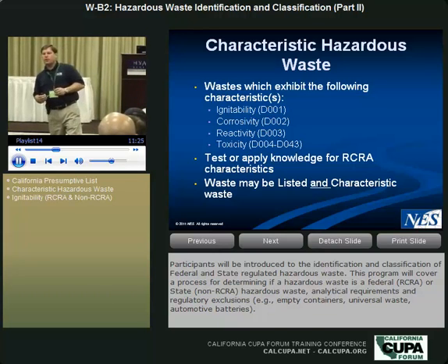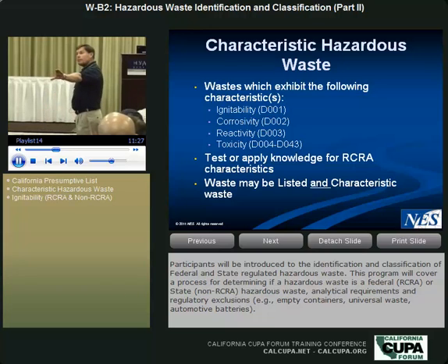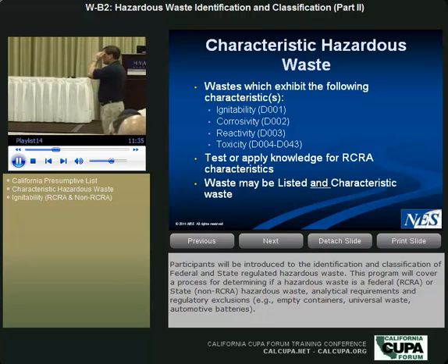In terms of corrosive wastes, some differences. But in terms of ignitable or reactive waste, they are the same. There is no difference. So these are our 4 characteristics: ignitable, corrosive, reactive, and toxic. Federally, if it meets the federal definition, which I will define for you here momentarily, we give it a characteristic code. It's a D code.